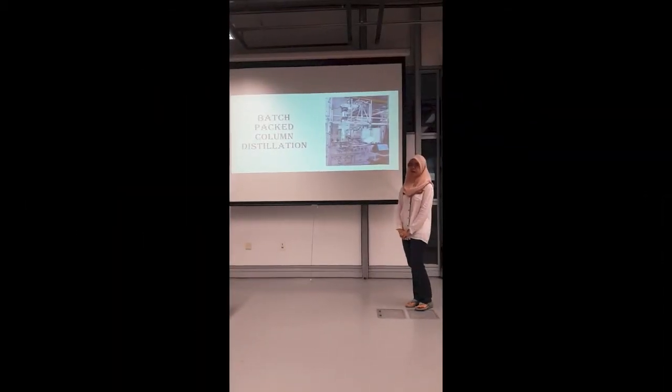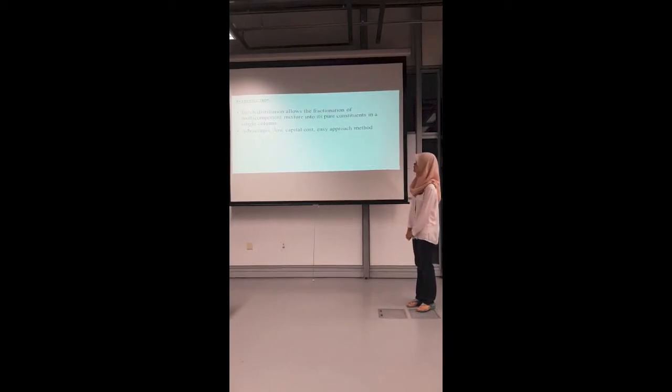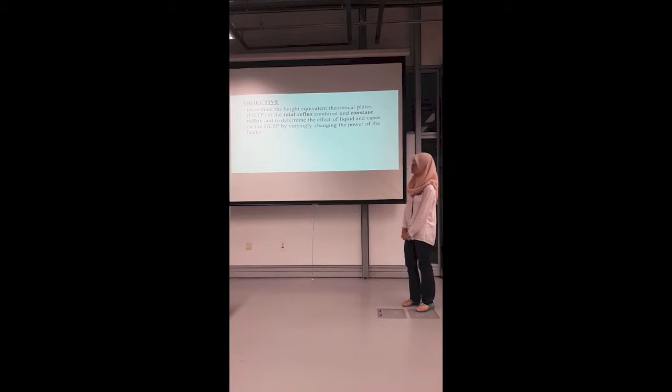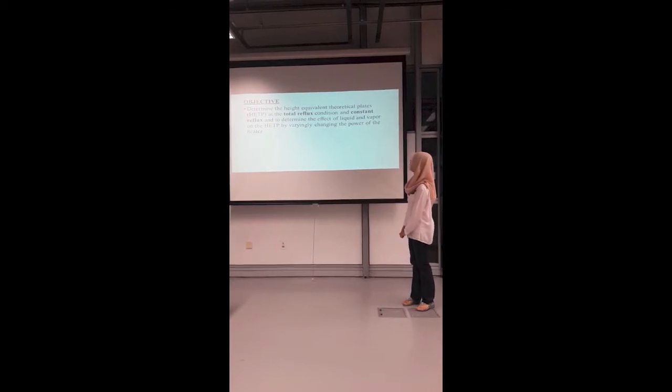Hi everyone. For the next experiment is batch packed column distillation. For the introduction, batch packed distillation allows the fractionation of a multi-component mixture into its pure constituents in a single column. The advantage is low chemical cost and an easy approach method. The objective is to determine the height equivalent to a theoretical plate, HETP, at the total reflux condition and constant reflux.